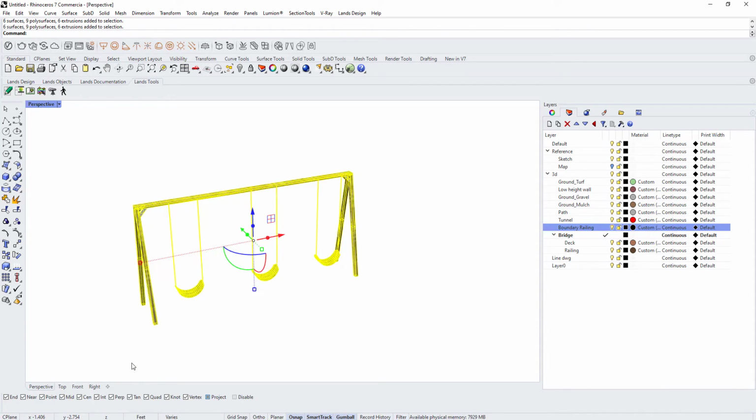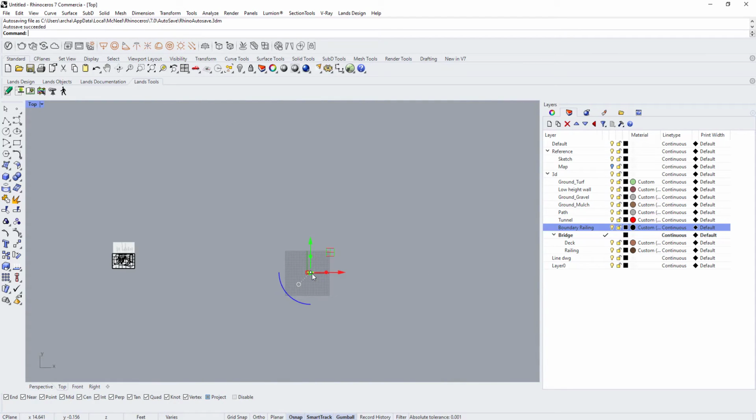Now, one important thing to keep in mind is that whatever you import might not be in a component mode, so you might have to group them from time to time. And keep that in mind for your complex layer too. Like for the bridge, you could group that as well. So I'll just type in group, that will make it into a group. I did not press block because blocks are sometimes problematic in my experience.